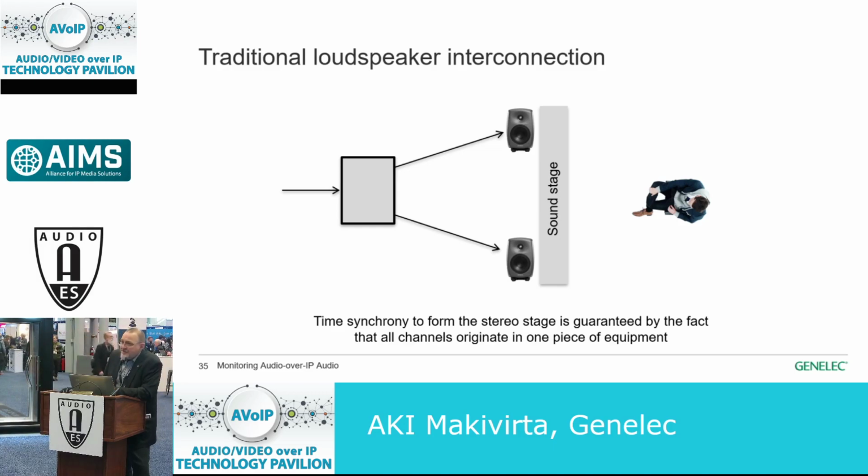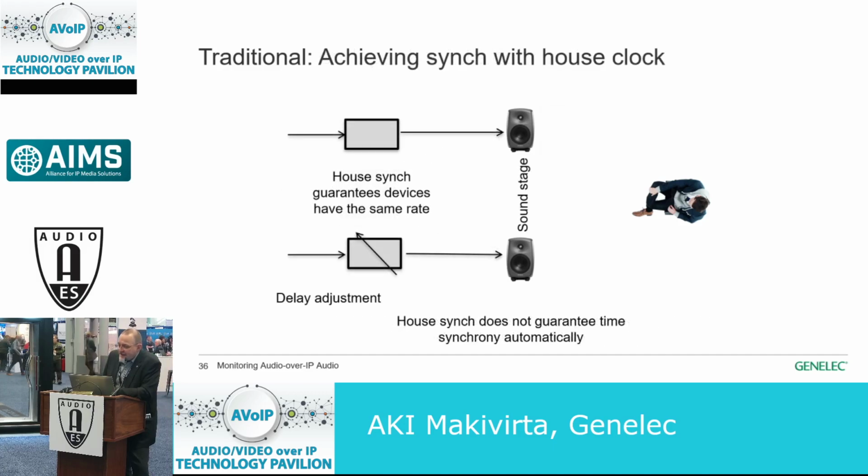If you don't have this situation and you are feeding multiple devices independently, providing signals for your loudspeakers, then you may have to synchronize your devices. For example, the traditional way of doing this is to use house clocking. The house clocking doesn't establish an absolute time reference. It does create an absolute frequency reference, and that's of course important.